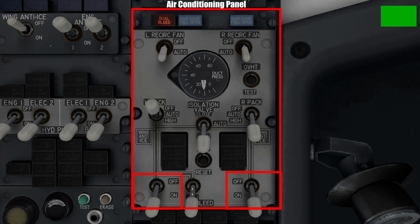When the engine bleed switches and the APU bleed switch are on at the same time, you get this dual bleed light, alerting the pilots that the pack systems are receiving bleed air from 2 different sources.